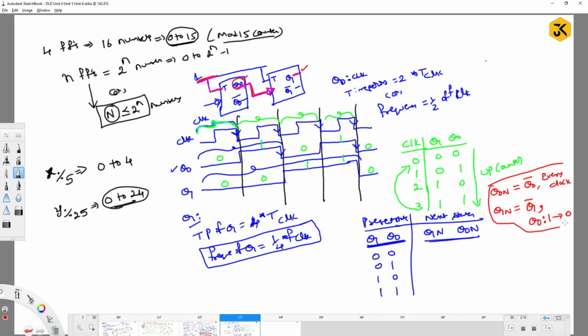So I have taken this concept in order to solve the GATE question sum. Above all things come under general things for theory perspective, but this particular concept is for the purpose of GATE. You can observe q naught n you are getting directly because of toggle of the earlier state, right? Okay. What about the q1? Q1 is also toggle of q1, but when is this q1 toggle going to happen? When the q naught is a kind of negative edge trigger. That is what I have written.